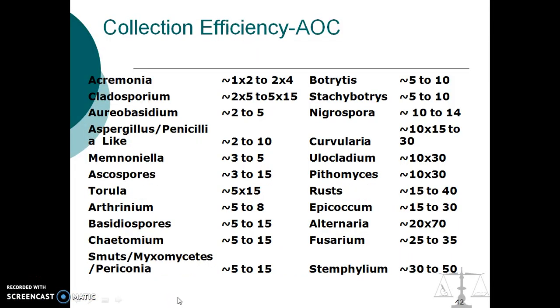All right. So again, we're taking a look at the spore sizes, the mass median aerodynamic diameter, and essentially when we see that the device has a cut value of 2.5 micrometers, well, unfortunately, a lot of our organisms that we're interested in are in that range, right around 2.5. And so this just simply tells us that if we're looking at a spore type whose mass median aerodynamic diameter is, say, 2.5 micrometers, if there's 1,000 spores per cubic meter of air, and we collect the sample, it's going to report it as 500 spores per cubic meter of air.